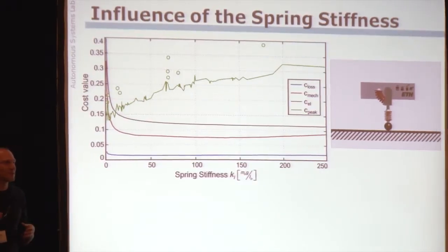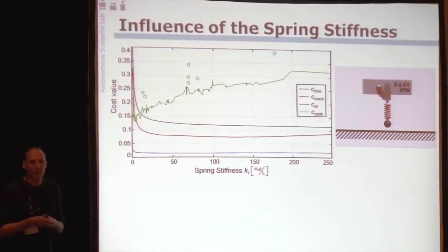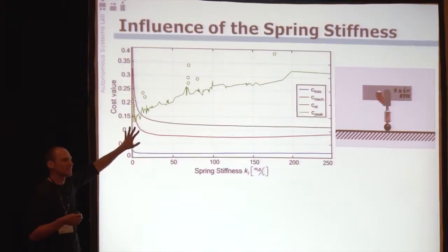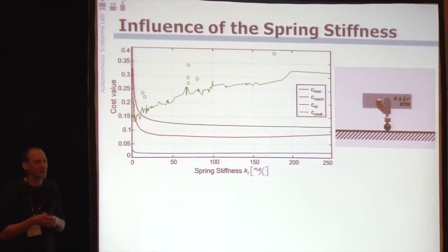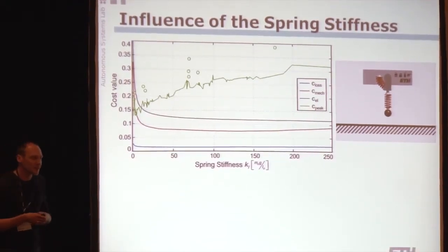Limitations in the actuators, torque limits and velocity limits, are of course a function of the motor power. And if you try to minimize motor power, you basically work on these constraints, which means this function doesn't behave numerically as well as the others, it's not as smooth. But I will try to convince you that what you see here makes sense.